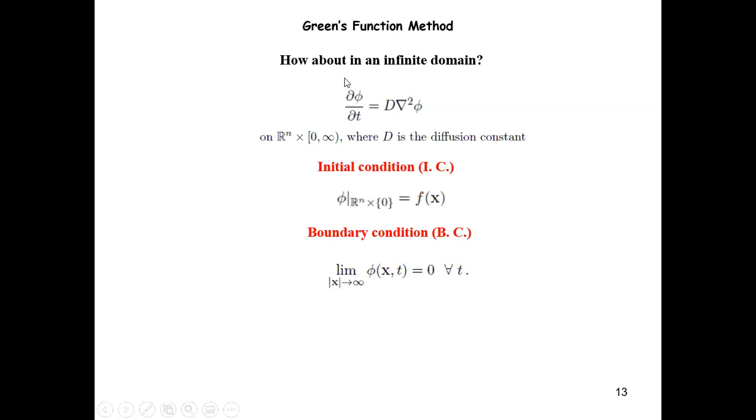So this is another way of writing the diffusion equation. Phi is nothing more than the concentration profile we have used as C, with its rate of change, and D is the diffusivity. This down triangle is simply a fancy symbol for the spatial derivative, but it can be generalized to higher dimensions, where we call it the gradient operator. The second order of this in one dimension is just the second order derivative with respect to x, and this is your concentration profile.